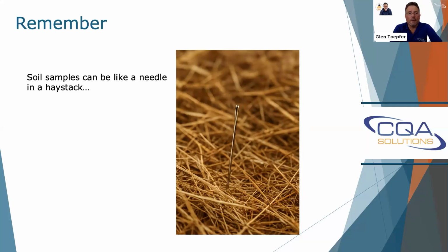People should look at the geological logs, the boring logs that are on site, and see what's there and adjust their sample plan accordingly, and adjust it according to what you encounter as well. Sometimes all the soils that you think are good aren't going to be good. There's going to be something there you didn't expect because it's between the borings.